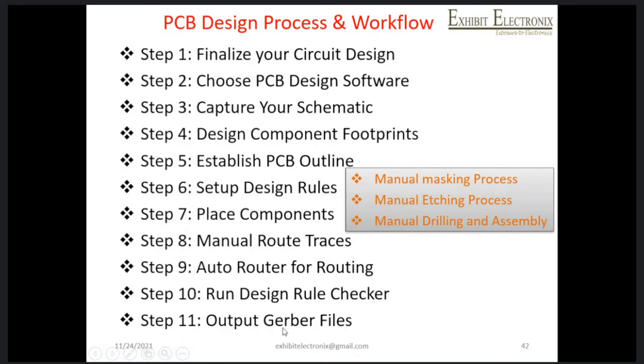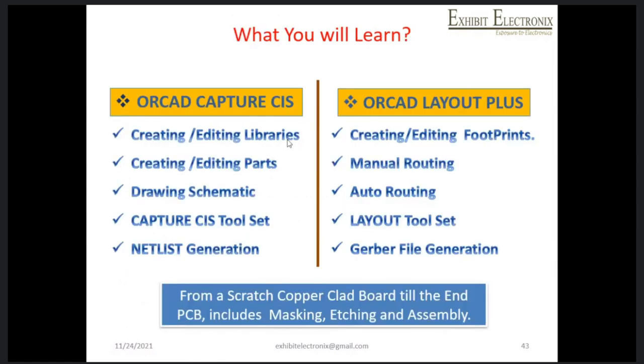The file we feed into a machine is called a Gerber file. Then the masking process, etching process, and drilling process are manual operations. We do some workshops in institutions on how a PCB can be made without the help of machines by students, on your own, only with the resources available in college. So if you don't have any PCB design machine, you can make it on your own. And I'm going to show you a video finally, of how you can do it with the manual process.